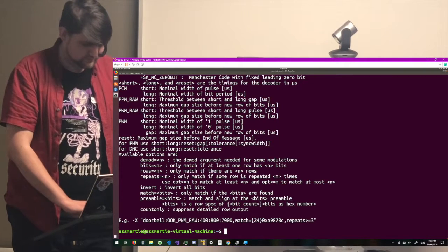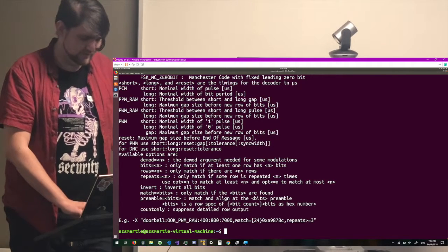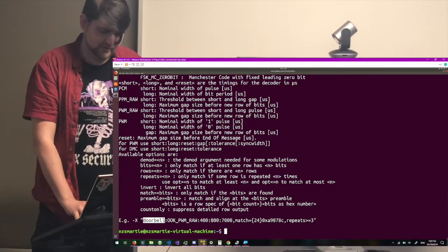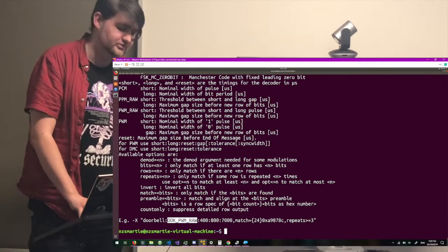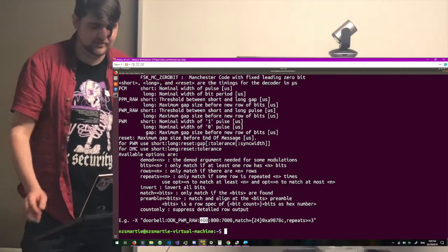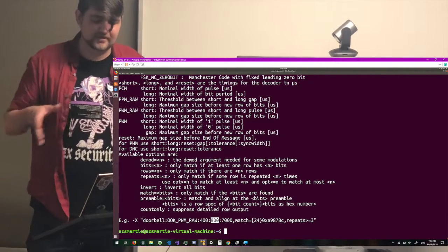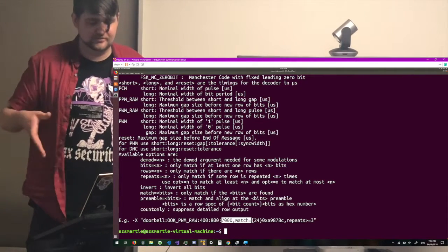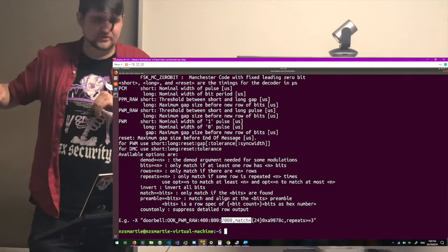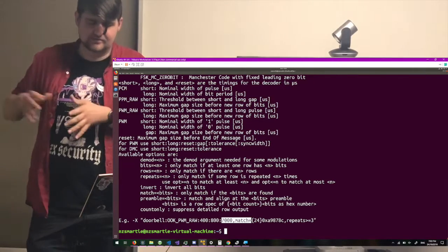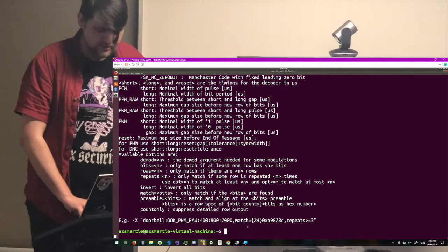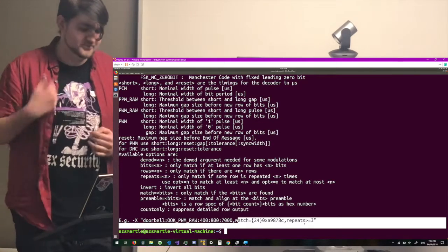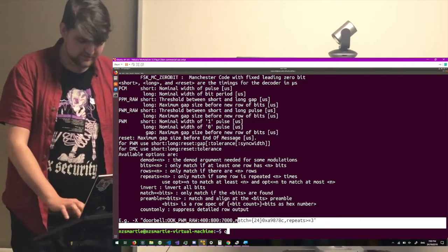So yeah, it says if you want to register a new spec, we'll call it Doorbell. This is an example string using pulse width modulation raw of 400 microseconds with 800 microseconds max width. So 400 is like a 0 and 800 is a 1, and then a gap. As long as the grouping doesn't space out more than 7,000 microseconds, they'll consider it the same message. This is just some additional filtering if you want to group repeating messages together, but we won't use that in this case.